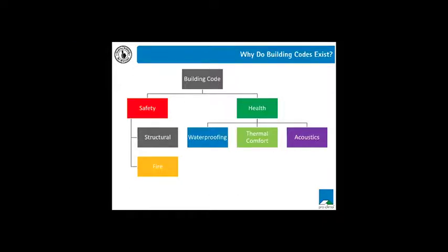So how do we do that? If we have a really poorly designed building, we throw energy at it to keep ourselves comfortable. We use heating and cooling systems. So that potentially leads to a perverse outcome, an unintended consequence of high energy use. So we have to design our buildings, insulate them, make the building fabric better to retain that energy.